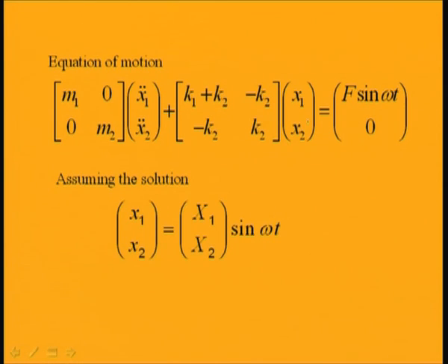And similar to the previous case, I can assume that this is forced vibration. So, the response frequency will be the same as the forcing frequency. So, I can assume a solution, [x1; x2] equal to [X1; X2] sin omega t. So, the frequency of the response equals the frequency of the forcing function.